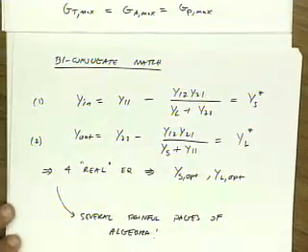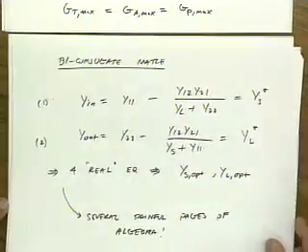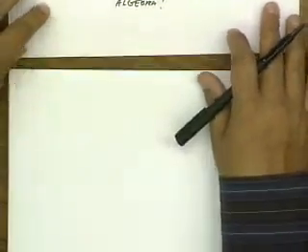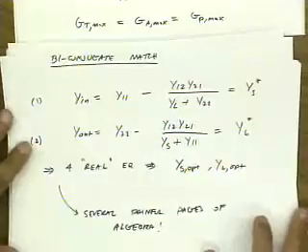When you're solving the equations, you'll run into a condition. You'll have a square root somewhere, and the square root has to be positive, and that gives you the condition under which the solution exists. That's exactly the condition we were talking about that could lead to oscillation if it's not satisfied. Okay, so this is one procedure for finding YS and YL.